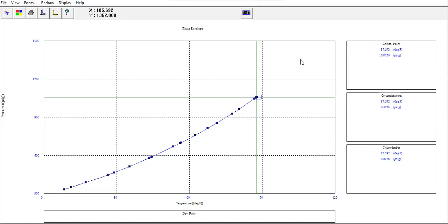And it is recommended that CO2 for CCUS, for CO2 storage, is injected in supercritical form, okay? So that we can store a huge amount of mass with small volume, because it's a dense phase. You can store CO2 at a high amount, huge mass, but the volume will not be that significant. But if it is gaseous phase, then the volume will be enormous.